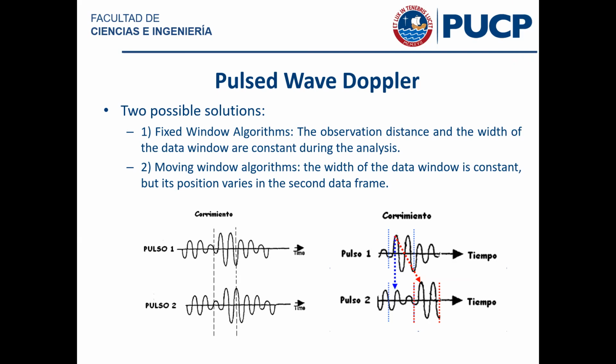That's amazing, because it means that, technically speaking, from the point of view of the signal processing, pulse wave Doppler has a perfect spatial resolution. You only need one sample. You don't need all the things to calculate anything. It's just one sample. That's awesome. Theoretically, of course. That being said, what happens if my signal shifts more than one period of the sinusoid from one pulse to another?